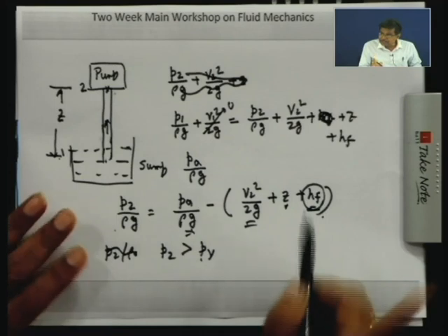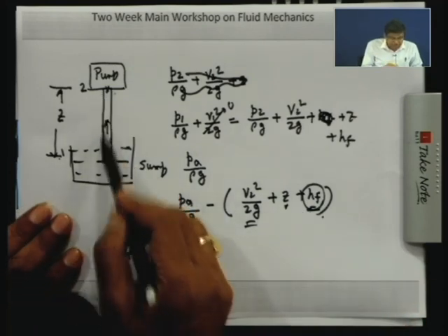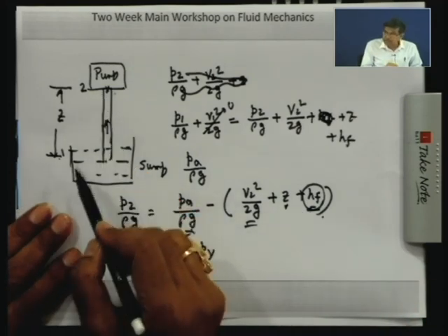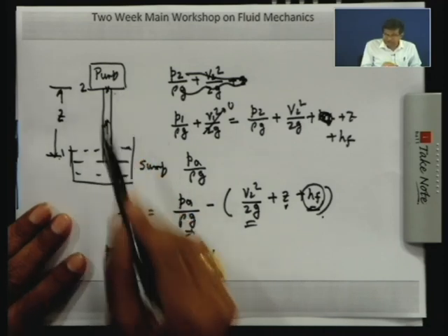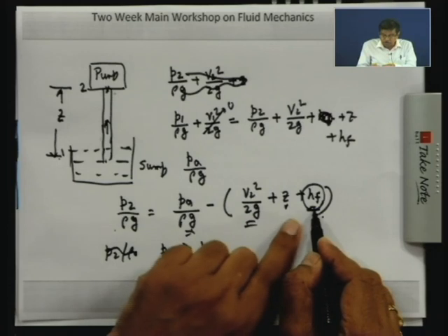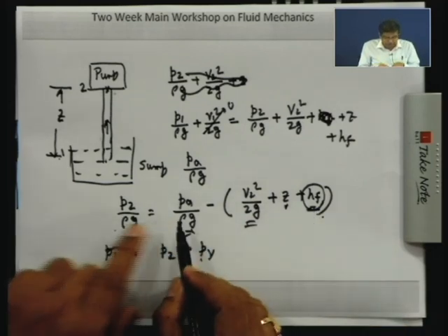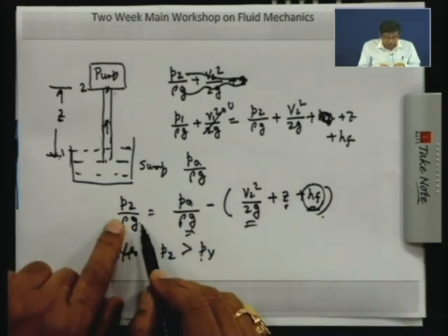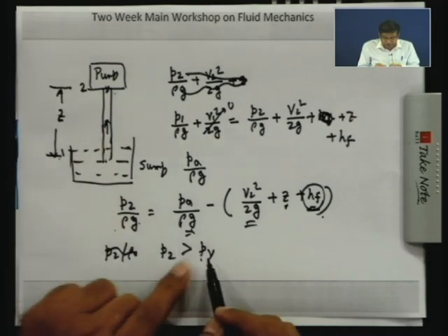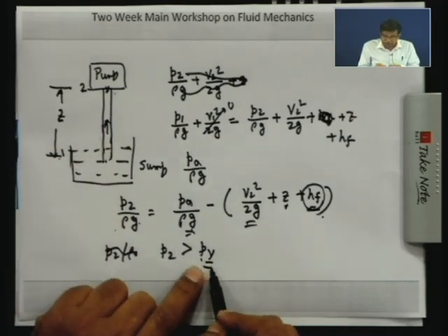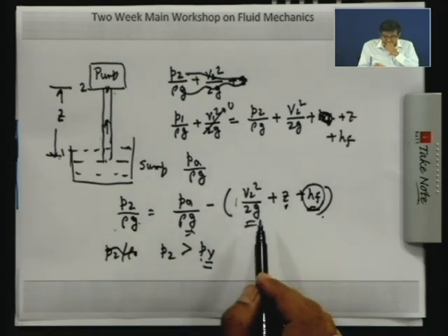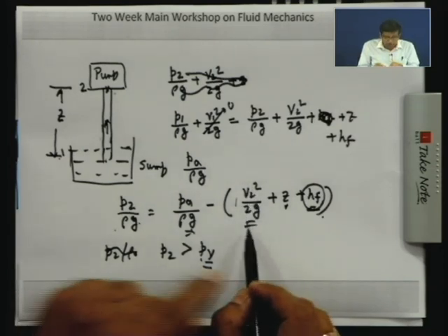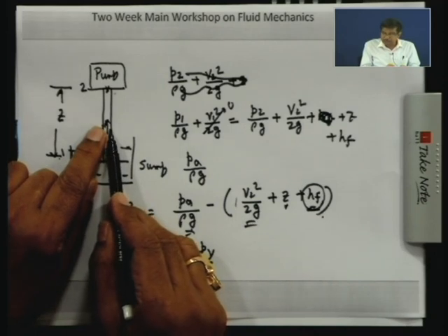This is the reason for which the suction side diameter is usually made a little higher, and we should eliminate all sorts of bends in the suction pipe, which would contribute to the loss, otherwise the suction pressure becomes severe, that means the pressure falls much below the atmospheric pressure, closer to the vapor pressure. Similarly the velocity of flow in the suction pipe has to be kept low, and this will be low if we make a higher diameter of the suction pipe.